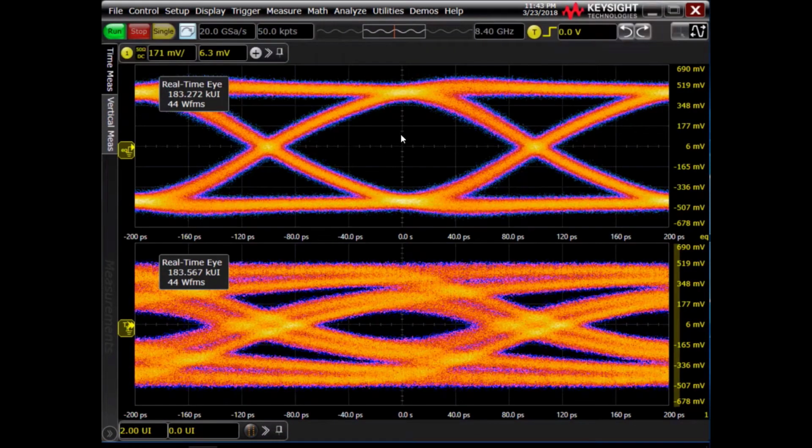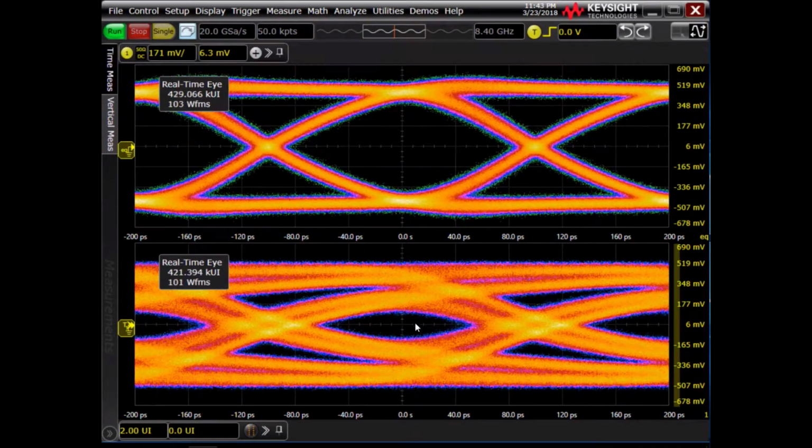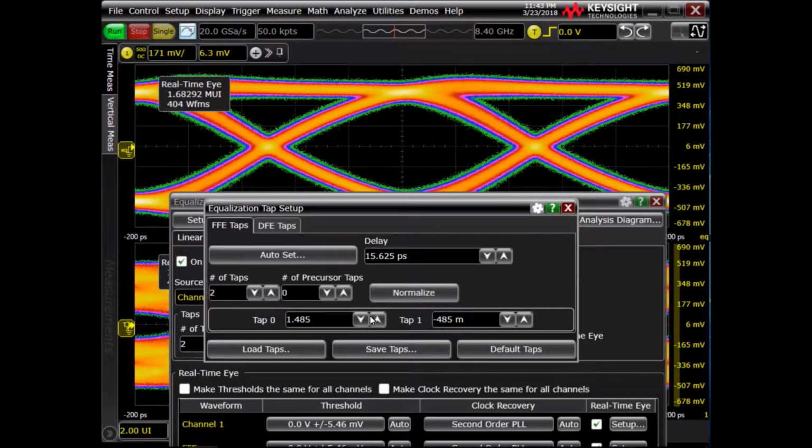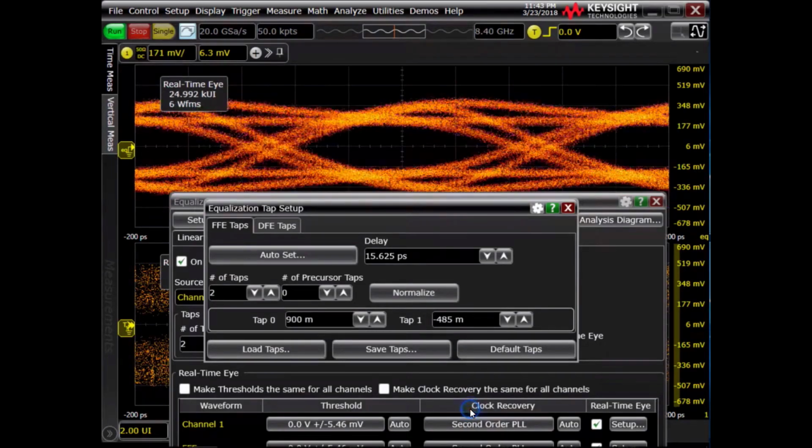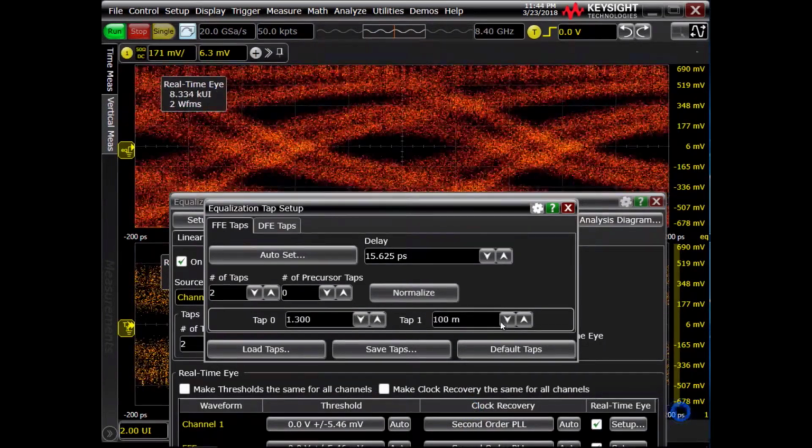Beyond that, even after all the processing we do, it's still not perfect, right? So in the old days, we expected the transmission to be almost error-free. In today's world, almost always when we're using PAM encoding, we're pushing so close to the limit that not only do we have to use a lot of equalization to open the eyes and extract the data, but we have to use error correction as well.